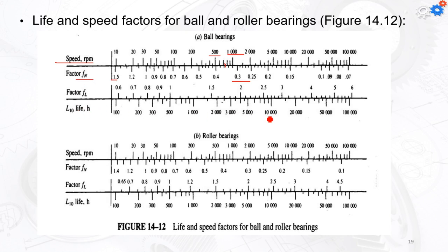For the FL, for 30,000 hours, that's 20,000, that's 25,000, that's 30,000. So we're looking at 3.95 or 3.9. Well, that's 3.2, 3.4, 3.6, 3.8. So it's going to be something like 3.9. So I'm going to choose 3.9. Now by having 3.9 and we have the Fn was 0.36, okay? By estimation, we can simply redo the calculation and find the answer.